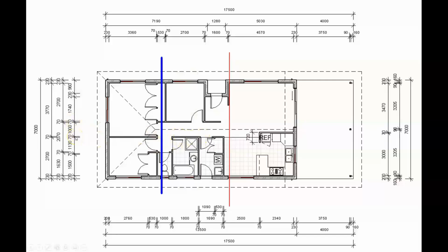So we need to look at some more walls that need to be placed. Keep in mind that the whole point of doing this line through the building is because this represents what the trades will actually do on site. When they turn around and they need to place a tape measure and then run out their tape measure to mark where these walls are going to come. This is why we don't have a line that steps at all, because we need to represent what the trades are going to be measuring on site in their straight lines across the slab.